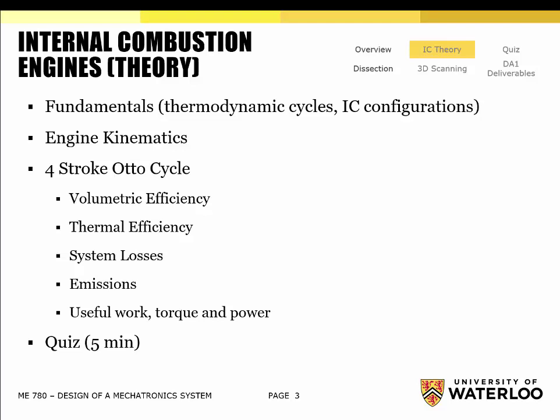Then we're going to look at the engine kinematics. The engine is a dynamic device that operates by converting reciprocating motion into rotating motion, so there's a whole bunch of kinematics surrounding how all the moving parts cooperate dynamically.